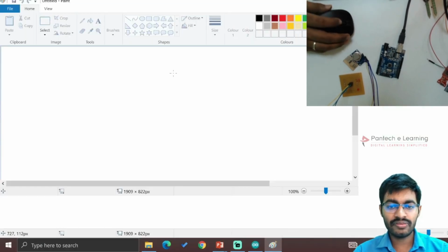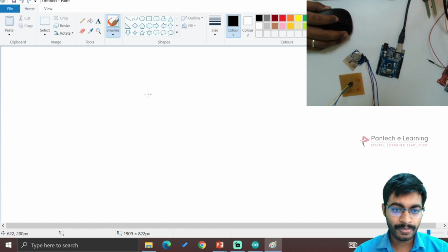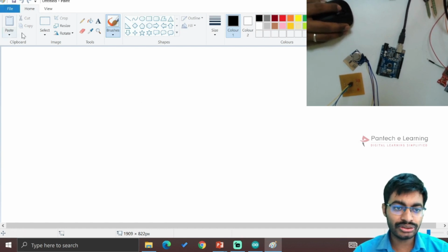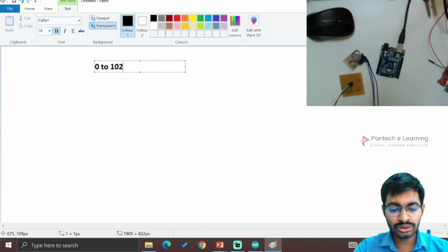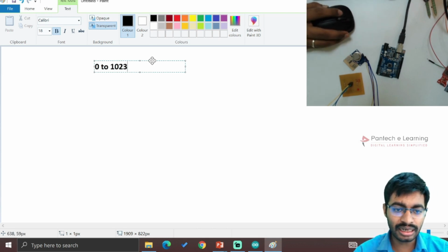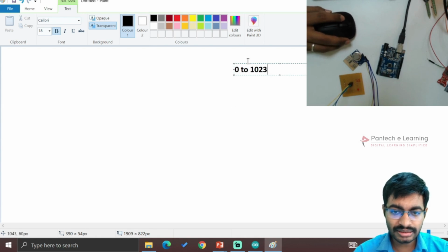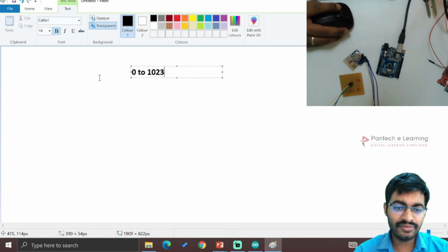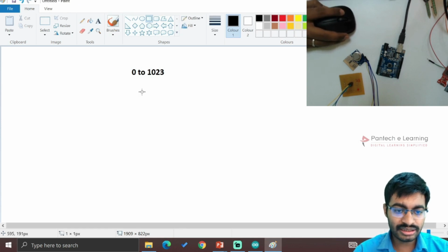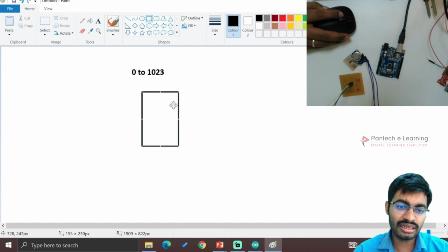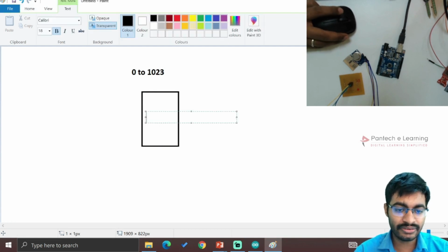Generally the analog waves are commonly said to be the physical one. Whatever analog waves we are going to see inside our controller will vary from 0 to 1023. So these will be the analog values which we will be able to see inside a controller. How are we able to get this? Initially we have the controller as a mediator section, but instead of going through the controller, we can directly make it the ADC itself, the analog to digital converter.